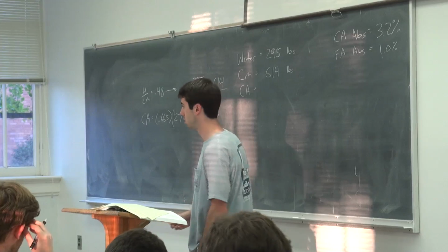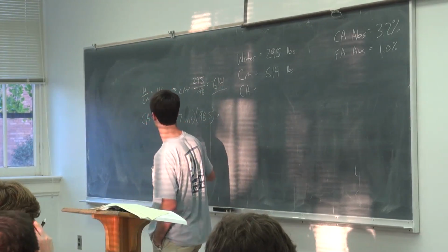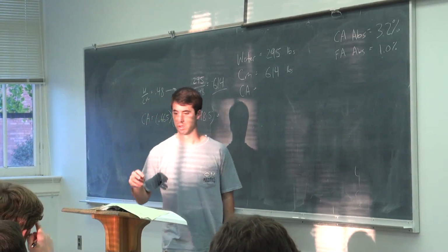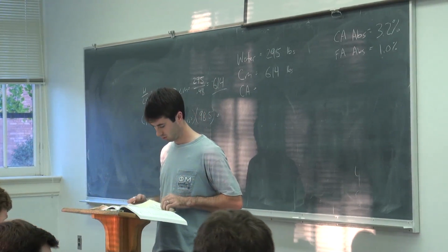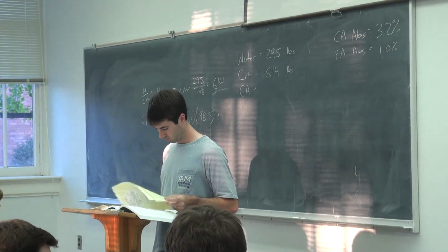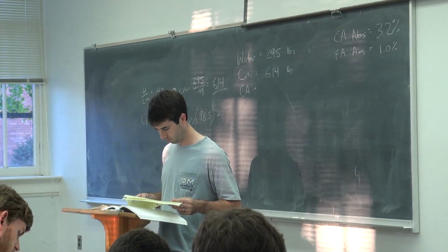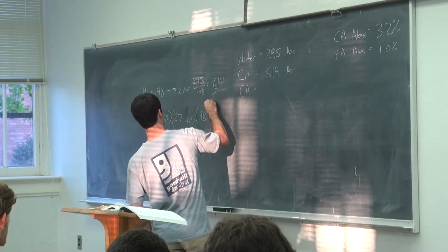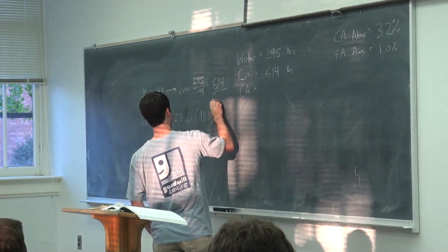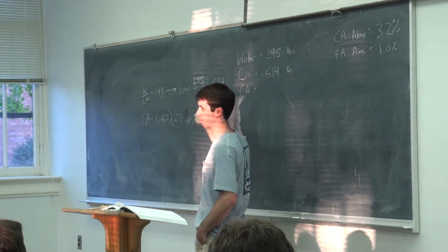I'm not sure where you get the 0.665. 27 cubic feet per cubic yard. No, because you're looking at a unit weight. This is pounds per cubic foot, I put it down wrong. The cubic feet cancel and you're left with pounds.